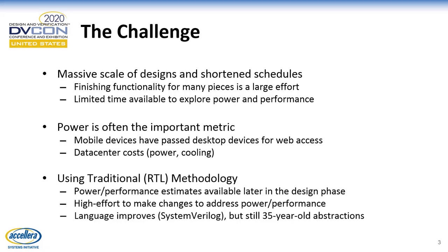And we're getting by with traditional RTL design methodology, but some of the big issues I see are your power and performance estimates are available pretty late in the design phase. What do you do with that? It's also often high effort to make any changes to address those and improve things. And the language we use improves a lot. I like SystemVerilog. I think it has some great verification features. But overall, it's the same abstraction as 30, 35 years ago, meaning you code what's between two registers.